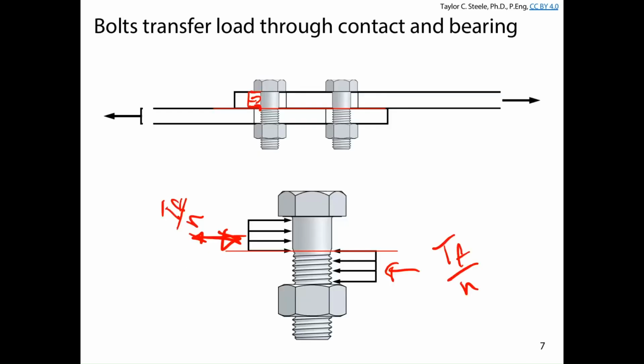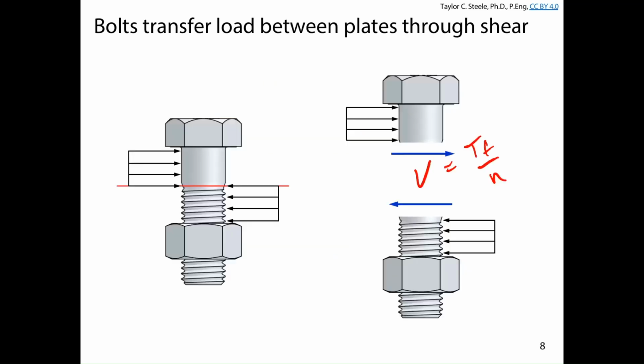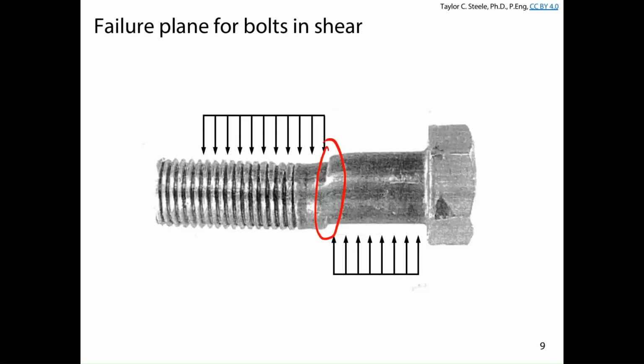Okay, so basically what's going on here is the tension member transfers the tension in the two components to the bolts through bearing. That results in a shear stress through one of the diameters of the bolt when we have bolts in single shear, and that can cause the bolt to start to fail on this identified shear plane. And it basically depends on the strength of the bolt and the area of the bolt, generally speaking.